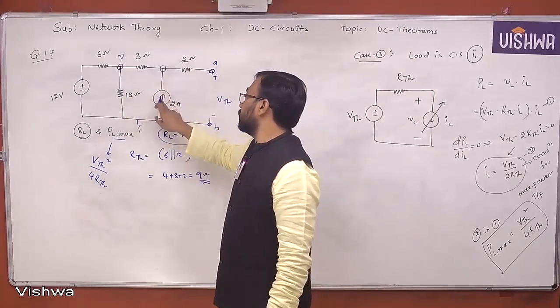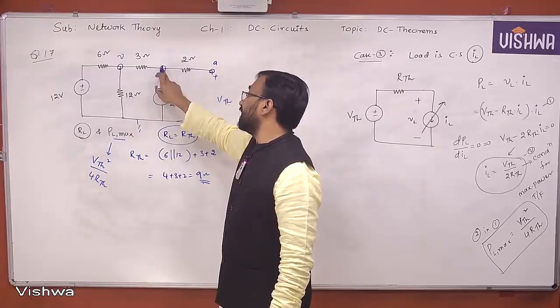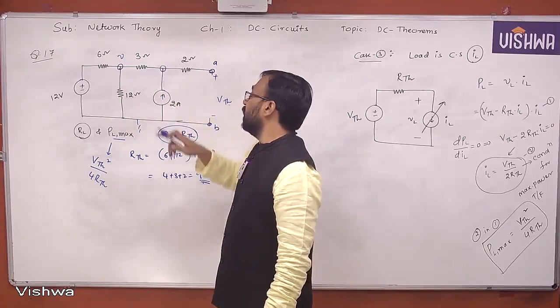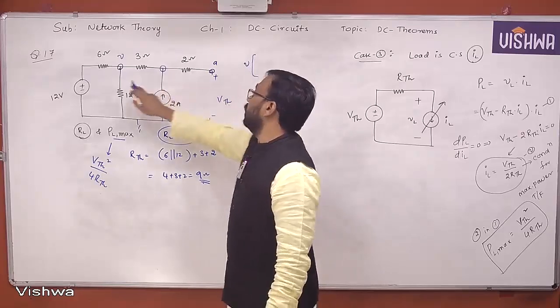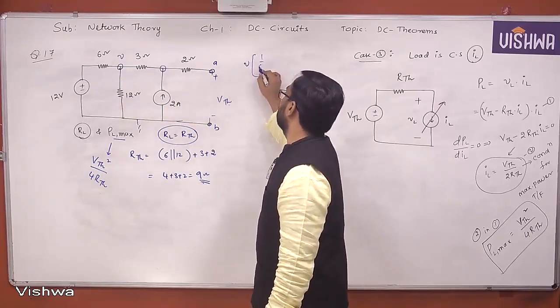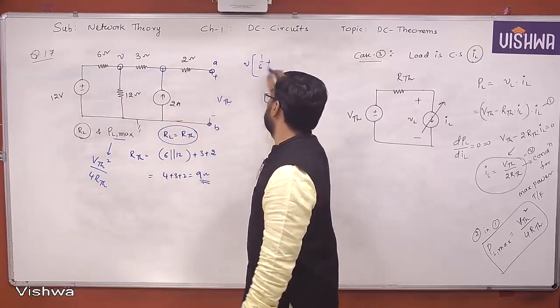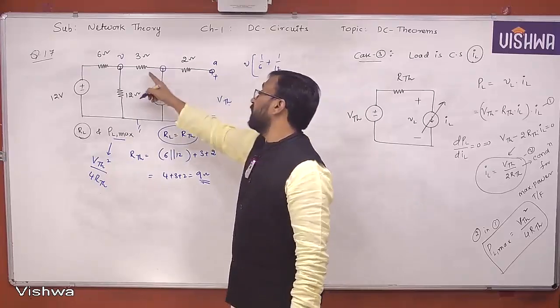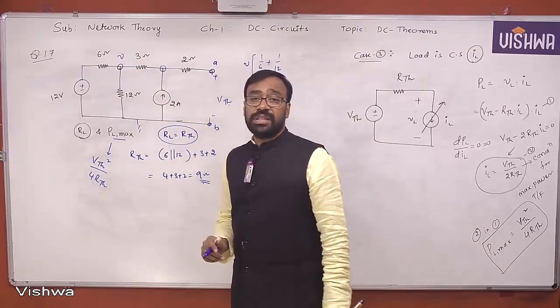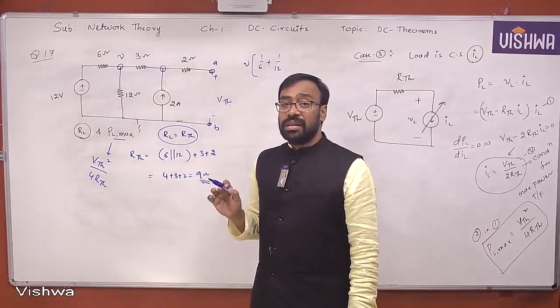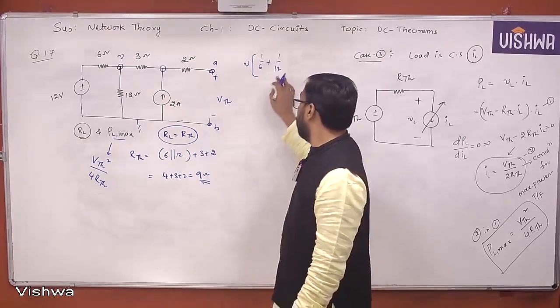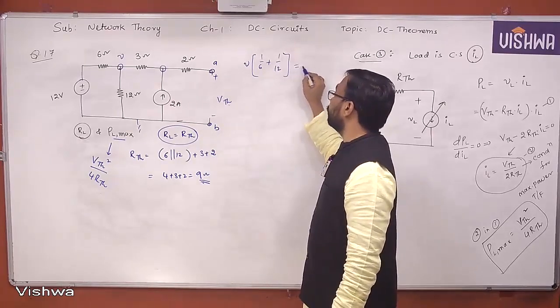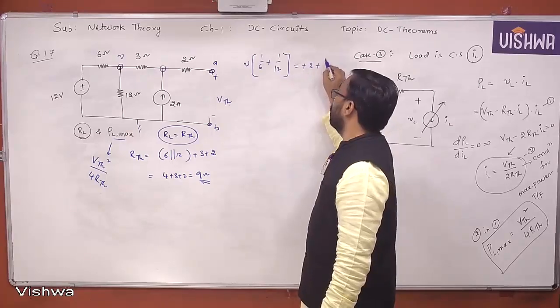And these two are in series. There is no need to take any variable. Let us not waste our valuable time in the simplification. So what will happen? V of 1 by 6, 1 by 12. Don't take 1 by 3, because the current source is already in series with the resistor. When there is a resistor in series with the current source, that should not come in this particular part. Yes or no? Plus 2, 12 by 6.